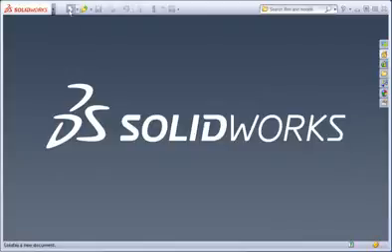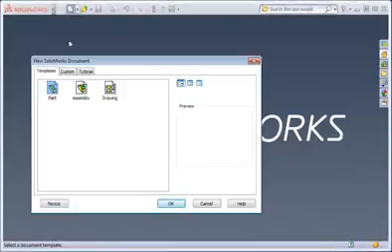Now click the New File command. As you can see, the new template is in the Custom tab of the dialog box. You can add more tabs to the dialog box by adding subfolders in the Custom folder. The only requirement is the subfolder has to contain template files. If the subfolder doesn't contain template files, it won't create a tab.